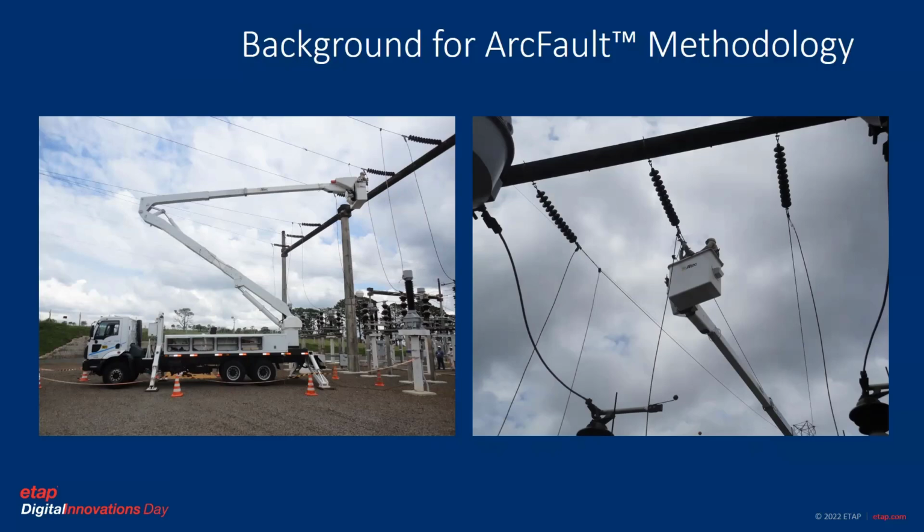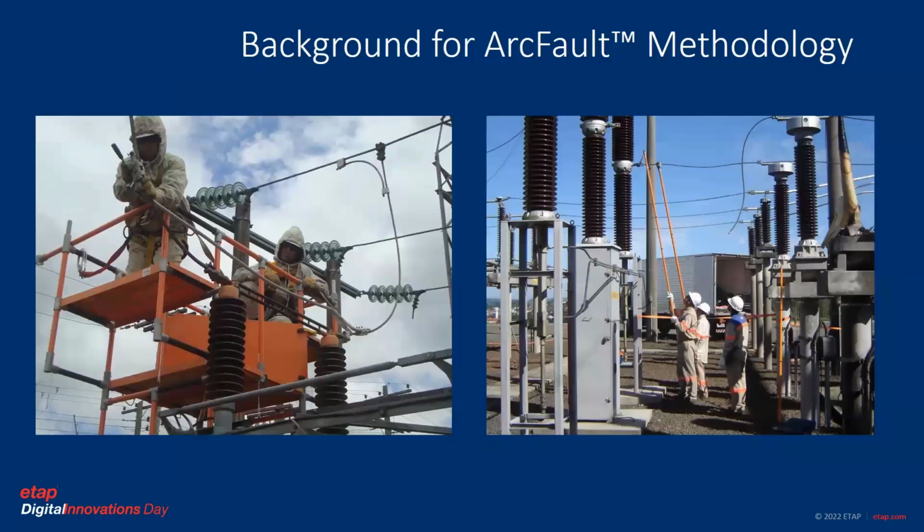Of course, live work tasks are not only required on distribution and transmission lines, but also in medium and high voltage substations. Single line to ground arc faults can be initiated, unfortunately, by line contaminants, by inadvertent human movement around the energized conductors, or simply by improper application of safety ground conductors.